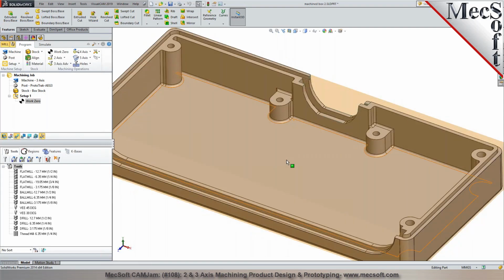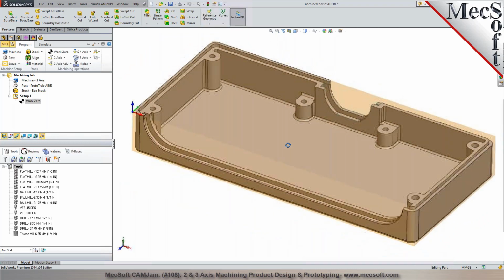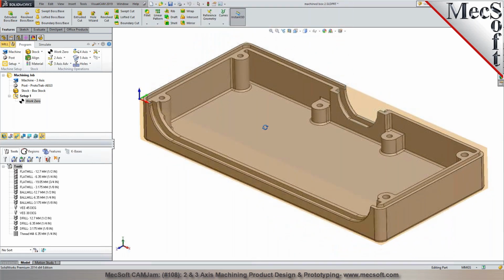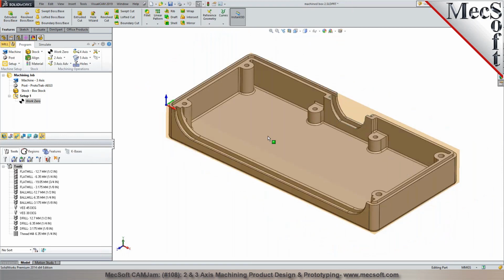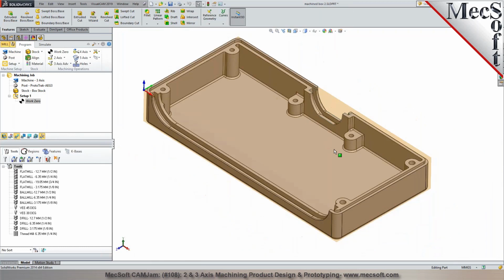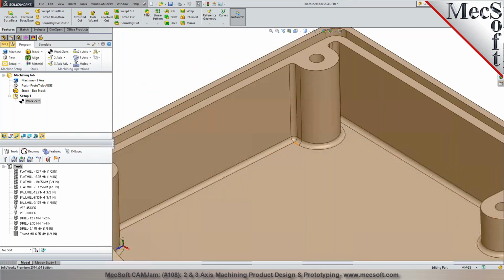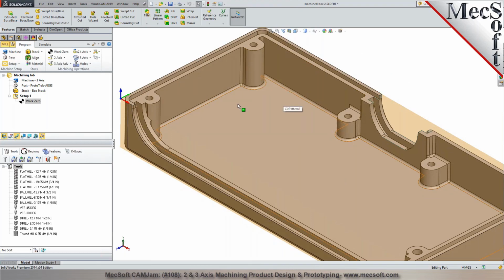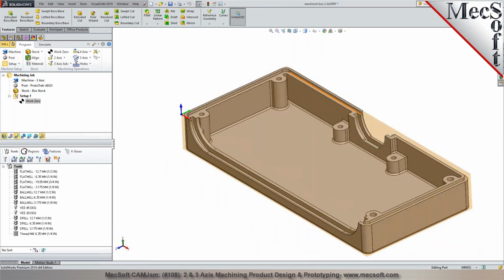In the next step, we're now ready to program toolpaths in here. So would you like to basically remove all the material inside this cavity in here, like a pocket? Yeah. Okay. So there's different ways you can program it. For prismatic parts, you could just do a 2.5 axis operation. Here you also have some fillets on the part. We could check the radius. Here, you have a radius of 1 millimeter. So if you want to just do a 3-axis operation to automatically account for all of these, you can use 3-axis operations to program it.